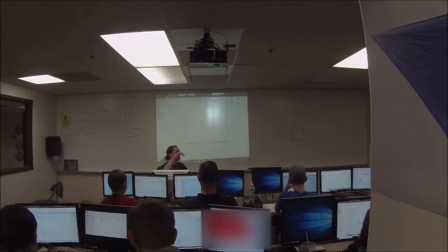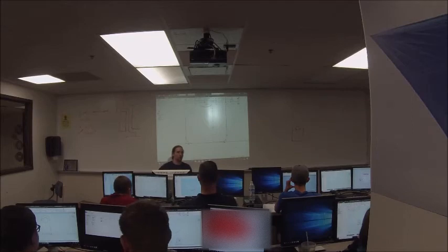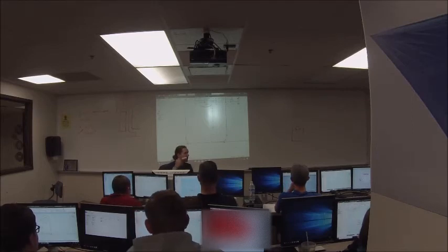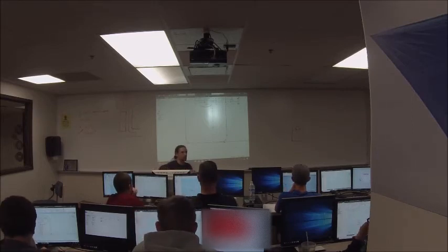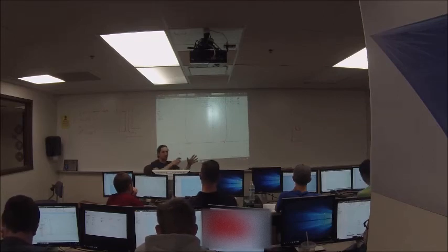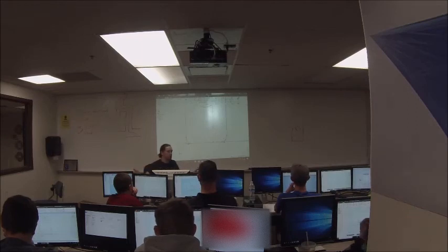When you're doing fillets and you do a bunch of fillets all in one go, Inventor will automatically place equals constraints between all of those arcs, which will make all those arcs the same size. So if for some reason you create a bunch of constraints and then you realize, oh, I don't want all of those to be the same size, I want to change just this one, you can go in, you can edit, you can delete the equals constraints out of there, and then you can attach a dimension to it.